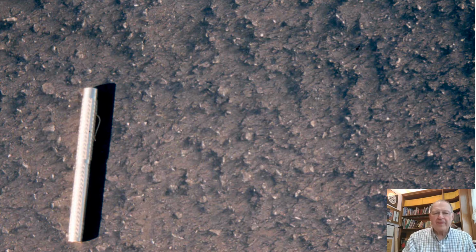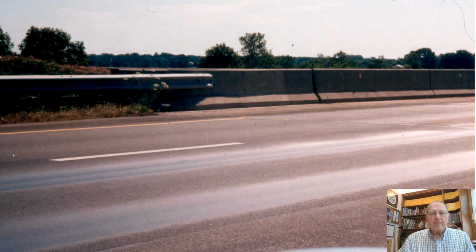So there's mostly bleeding that is taking place in this example. And that was because there was a mill and fill and the lift thickness was thin. As a result, the excess asphalt in the mixture only allowed it to densify and squeeze the extra asphalt out through the surface, but it didn't cause rutting to take place.